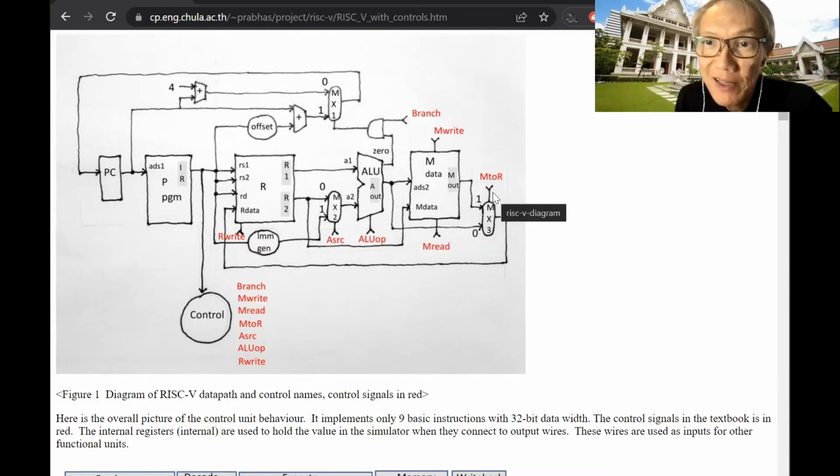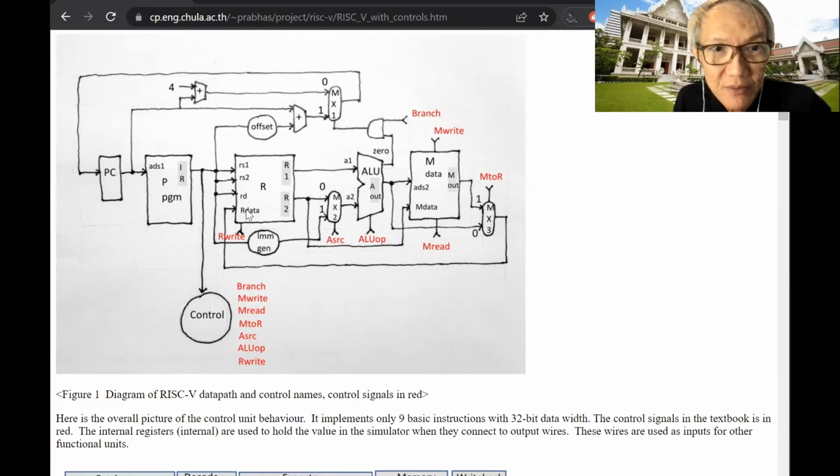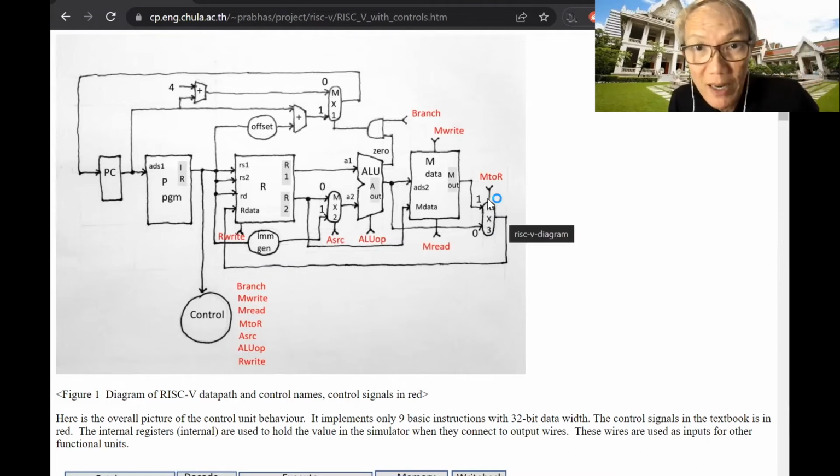Okay, we will talk about the write back. The last stage is that we have to update the destination register. We have the wiring of the output going directly to the register bank, to activate writing, updating the register bank. This information can come from 2 sources. One is just from the memory, which we call mout, right? This one must be the load instruction. And if it's not a load to register, then it has to be some register type instruction, right? Choose the value of the output of the arithmetic logic unit here. Whether we choose memory or register depends on this control.